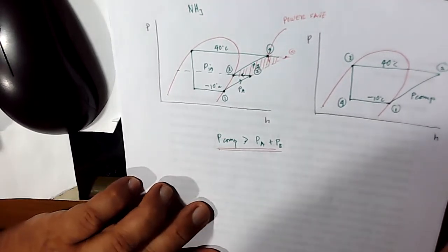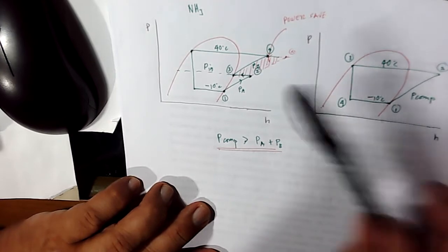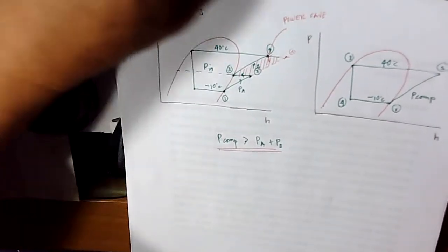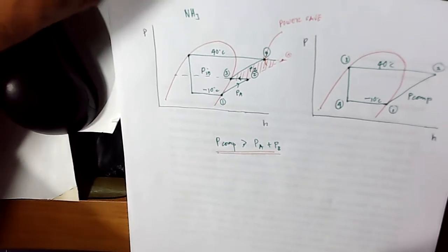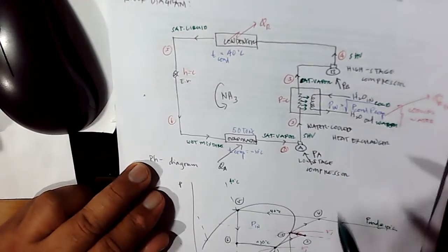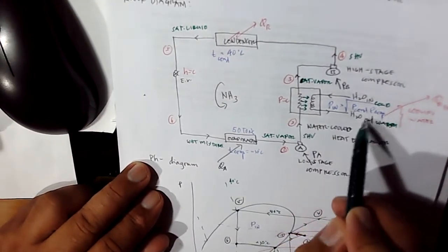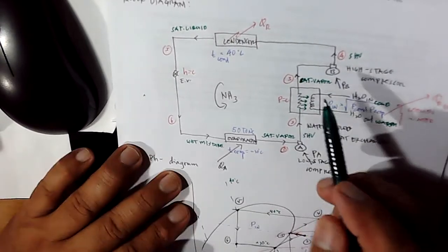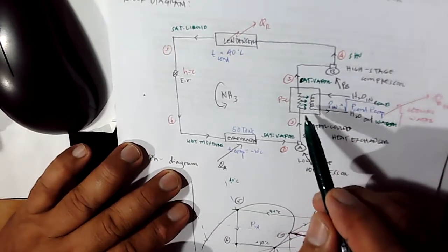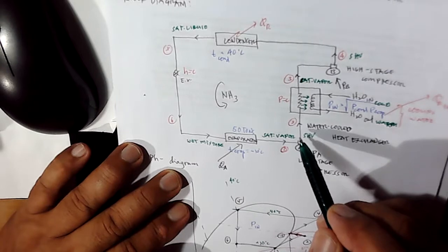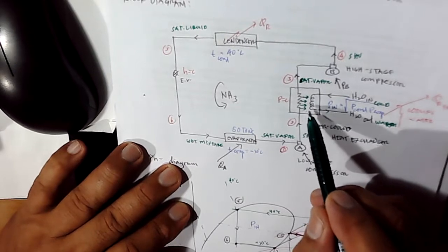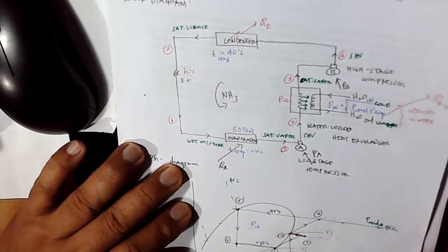Okay. Now, this system using a water-cooled heat exchanger is, as I said last time, considered a closed system. Closed in the sense that the water coming from the cooling system does not mix directly with the medium coming from the refrigerant system. It only absorbs the heat coming from the refrigerant side, absorbed by the cooling system, and rejects it to the atmosphere.